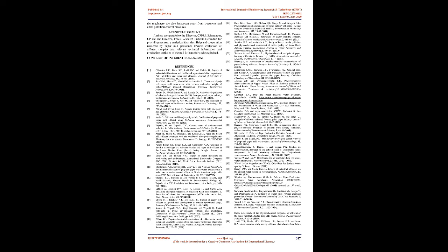Effluents from all the units exhibited BOD values much higher than the prescribed limit of 100 ppm, 100 mg/L, for safe disposal of effluents as per Indian standard, IS. The high biological oxygen demand and coupled low oxygen content of effluents affect the survival of aquatic animals of the receiving water body. 36. 8. Determination of COD. The amount of oxygen required to break down both organic and inorganic matter is termed as chemical oxygen demand, COD, which is one of the important indicators of pollution load in effluents.